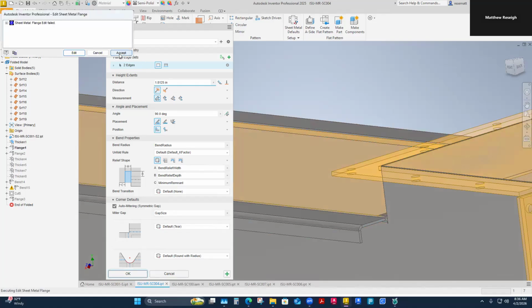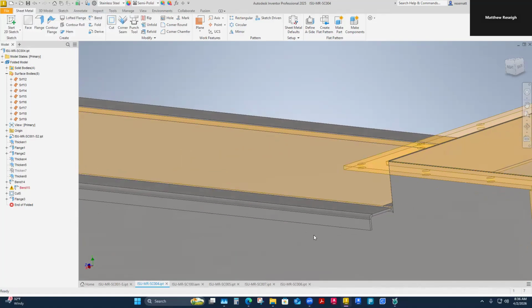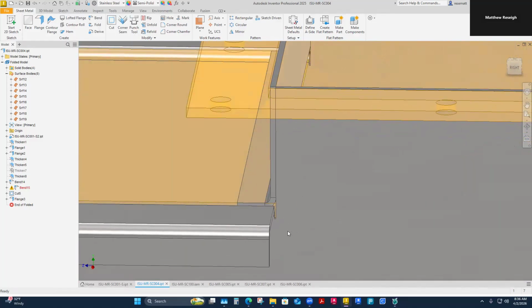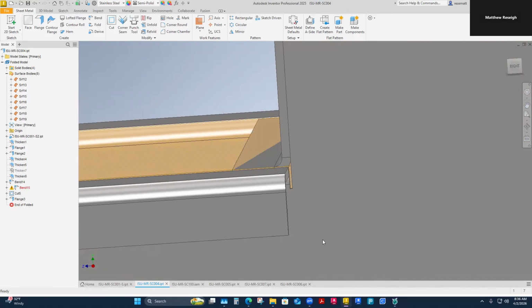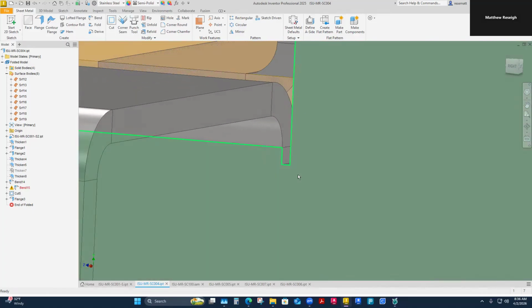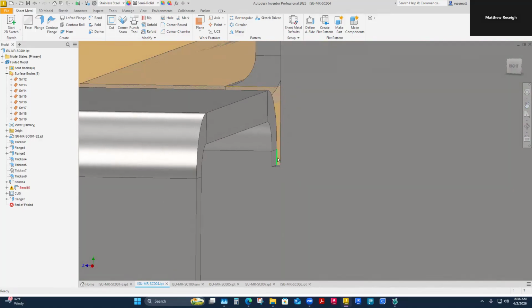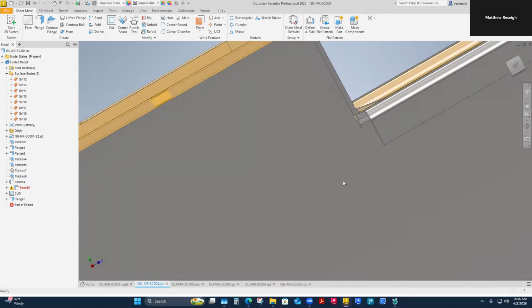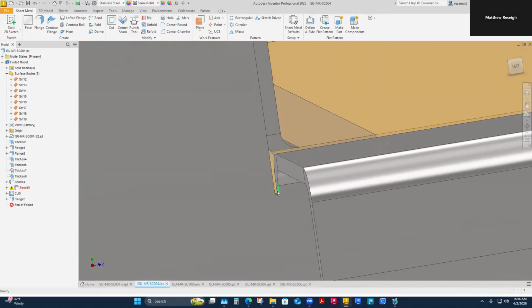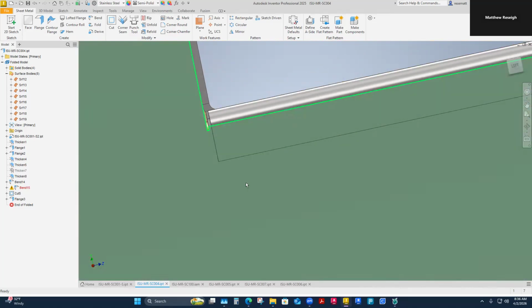And then you may get something to blow up. Just say accept it and we'll work that out if something does blow up. But what I'm looking to create is just a little separation between those two. And that bend width, the other relief that's being cut, is from here to here. I could decide later that I don't want this either, but I'm going to leave it in right now. So I'm letting the default like that. The B variable in that little selection is how much this is cutting into me. I did both those flanges on the same command, so it should have done both sides.